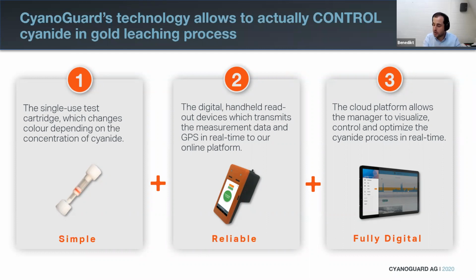And what you then do is you take this cartridge and insert it in our handheld analyzer. It looks like this. Turn it on. And then you select the cyanide analyzer function on the device. You select your range. The ranges are of course customizable, but this is just a demonstration so you understand how easy it is. We select the 10 to 100 ppm, we press measure concentration, it takes a few seconds, and then it displays the result. In our case, that's 20 ppm free cyanide.